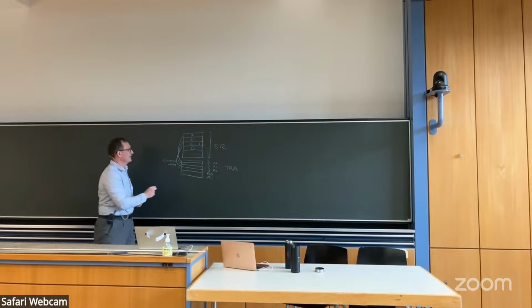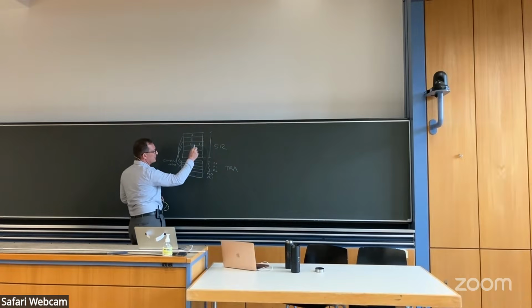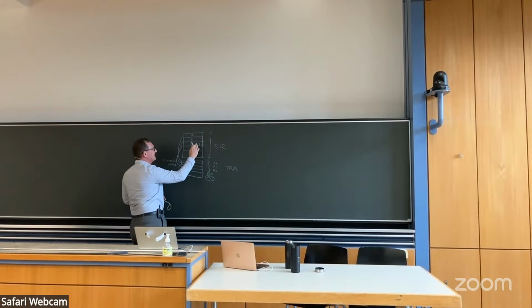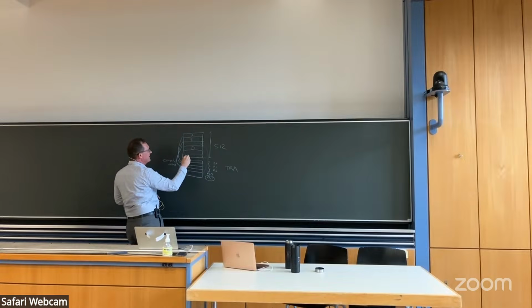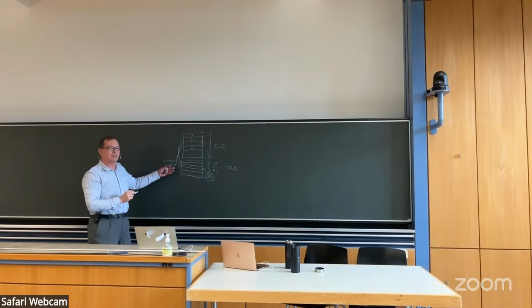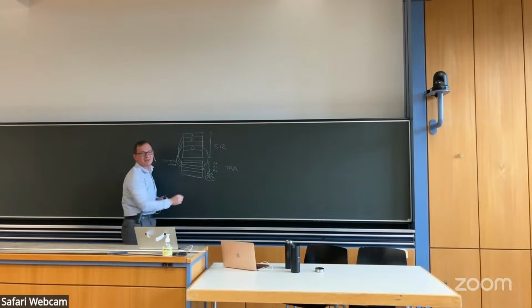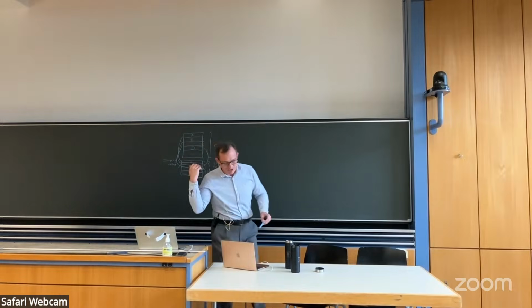So with a few RowClone operations, 1 RowClone operation to move it from here to set C to 1. Actually, you don't need that if it's here, right? You don't need to move that again. So you can eliminate that. Basically, if you're doing just an OR operation, you can move A here and then B here, and then you can move reserved row here, and then you can do a triple row activation and move the data from any of these to a destination over here. Okay, that's the idea. If you do majority, you do something different.